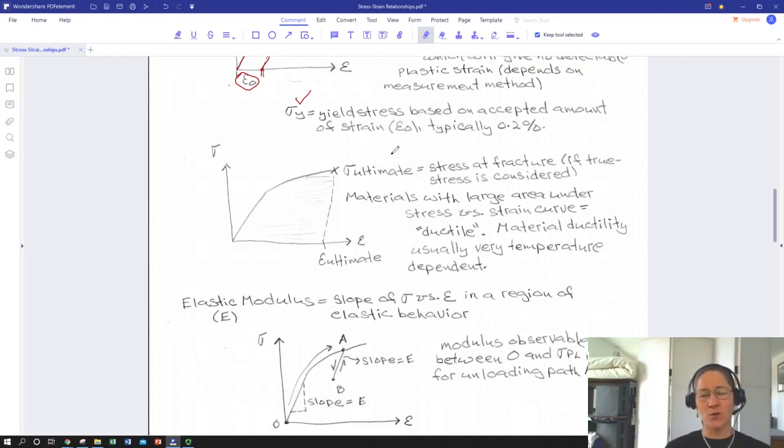A general rule of thumb is materials hold in compression, they break in tension, they yield in shear. And that last one is one that we'll base a yield criteria method on, that we'll get to after we look at stresses and strains at different orientations within a material. But if we put something in tension, especially in bending, the tensile side of a bending sample, we tend to open cracks, and they'll propagate more easily than we can get all of the deformation mechanisms going.